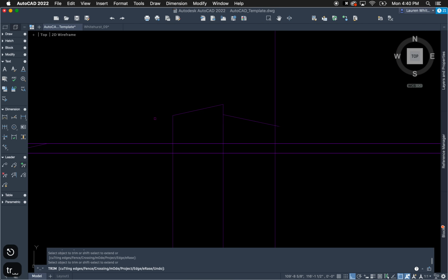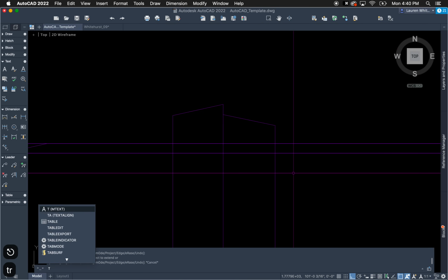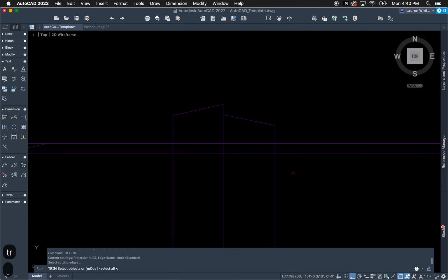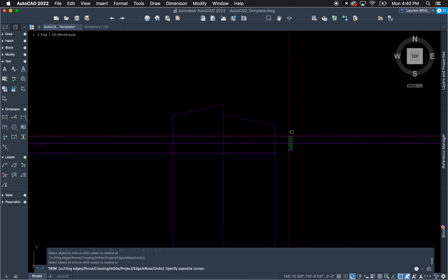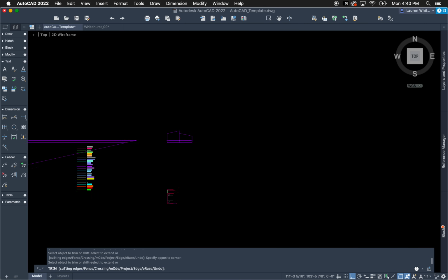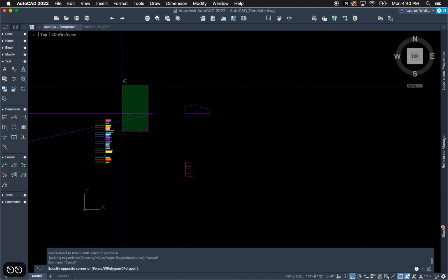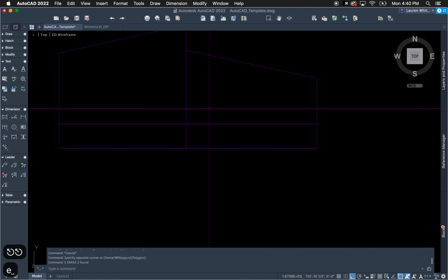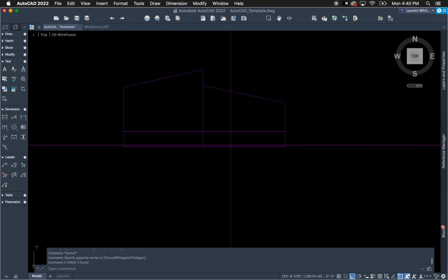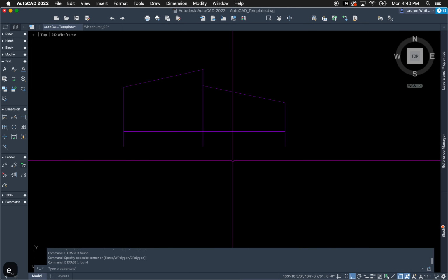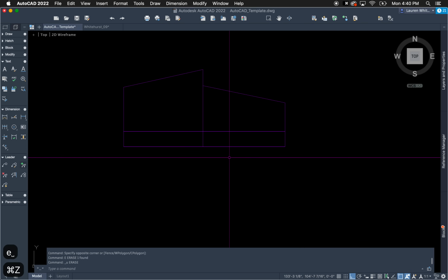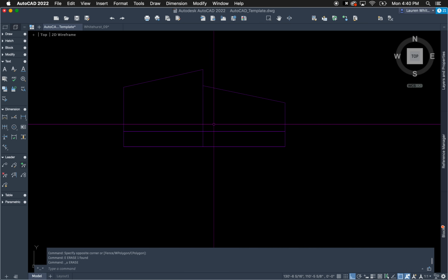But so this was my house. I'm just trimming. To trim quickly, if you type trim and then hit space and then space again, it will trim anything that's intersecting. Notice how it trims everything that's intersecting. So these lines here trimmed, but erase is E, it's another good one. E for erase, so select something, hit E, space, and it goes away. Control Z is undo. There's a couple other useful commands on the assignment sheet, so check that out.